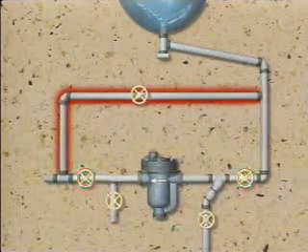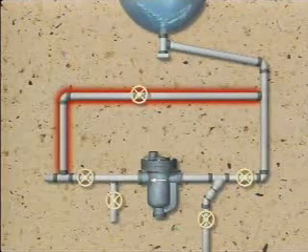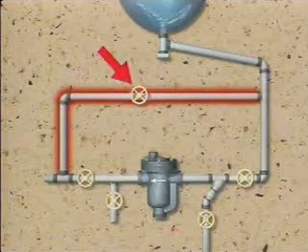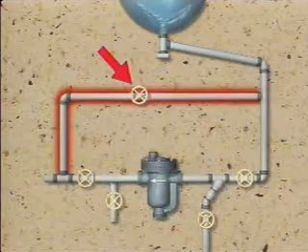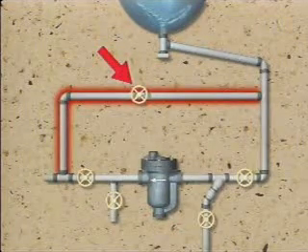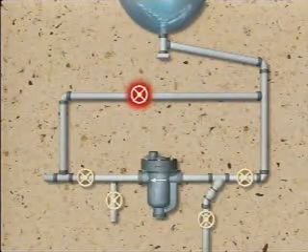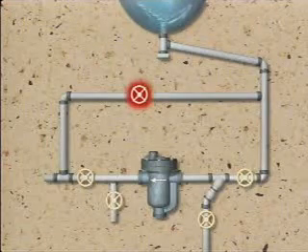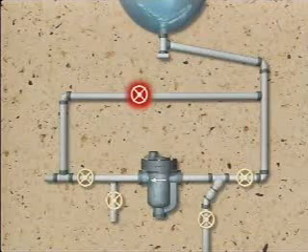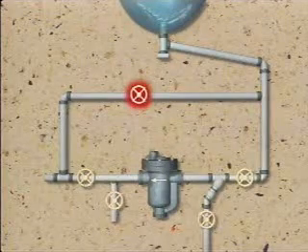A bypass line is also included in many steam trap stations. A valve in the bypass line enables workers to bypass the entire steam trap station if necessary. The bypass valve is usually opened when there is a suspected problem with the trap. Opening the valve may be necessary to keep the facility operating, but as long as the bypass valve is left open, steam blows through the bypass and the efficiency of the steam system is reduced.